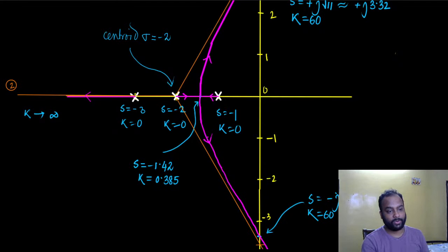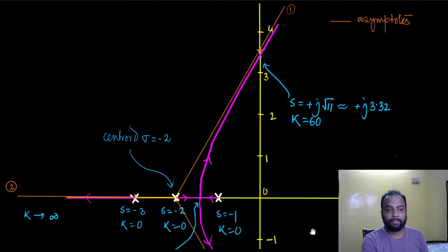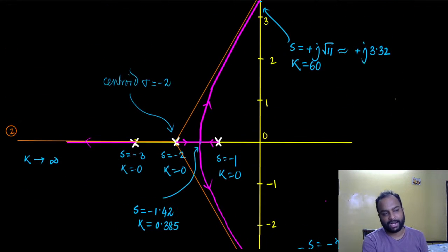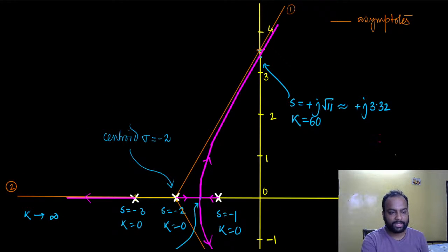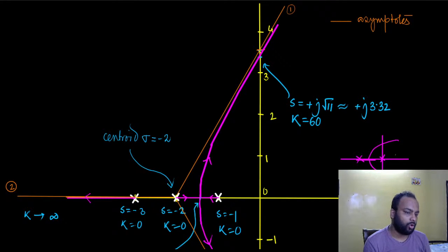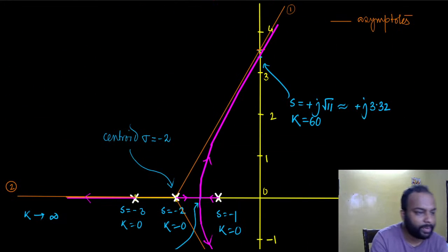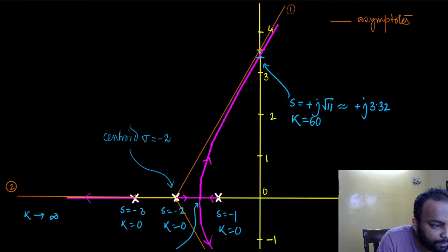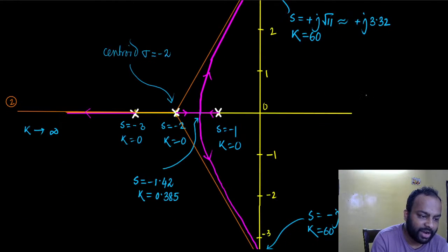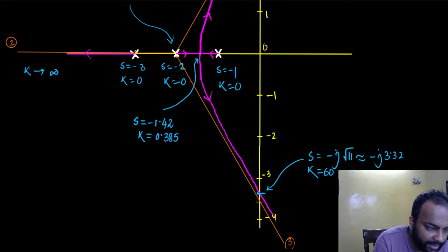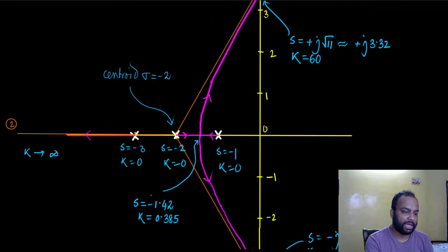All right, so now we have a better drawing. Just keep in mind that in the previous drawing, I said the curve was not right because I had drawn it this way. We had two poles meeting each other, and then I had drawn them like parts of circles or something like that. No, they have to follow the asymptotes, and the asymptotes have to be their tangents, right? So now look very carefully. They are crossing over the j omega axis at those precisely defined points defined by rule number 4, and they are following the asymptotes as per rule number 5.